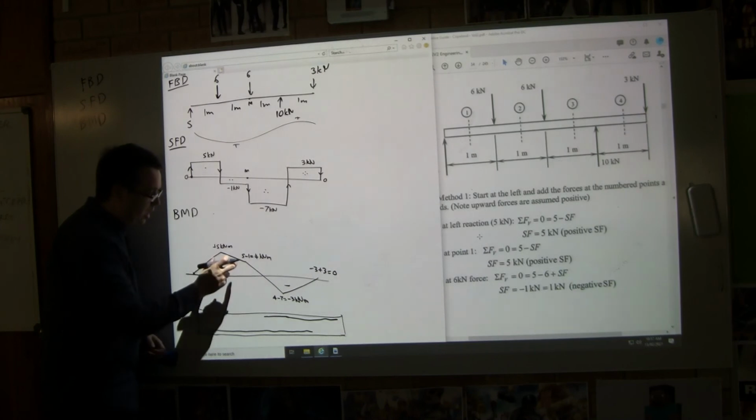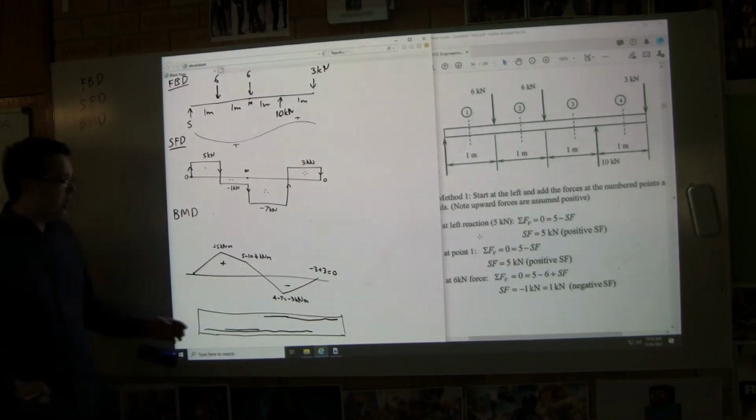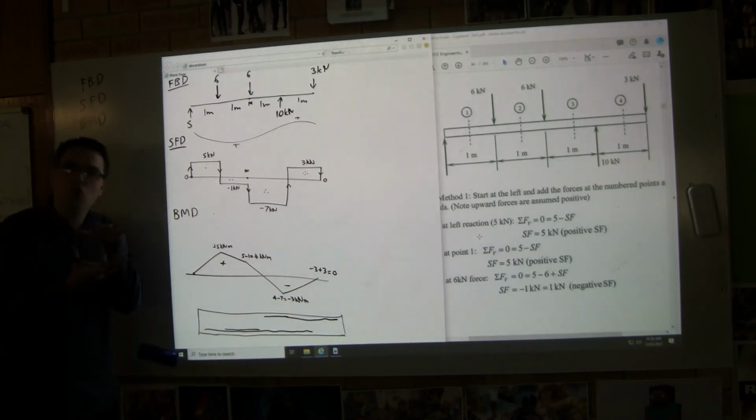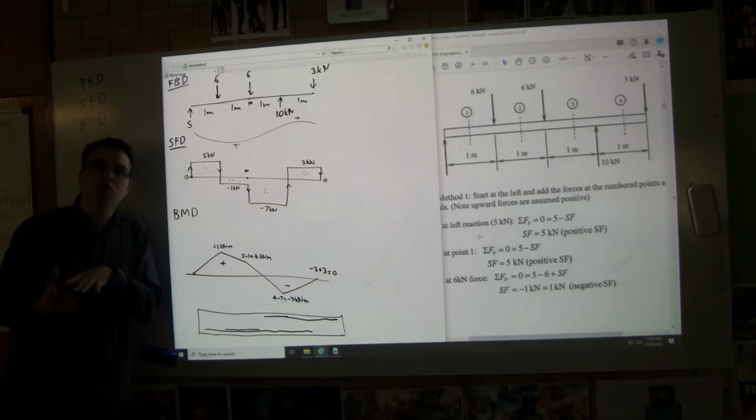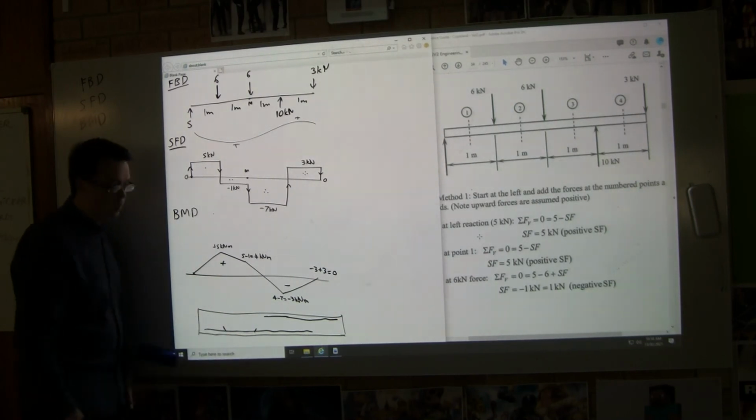Now, because our maximum is here, we might add some extra steel in that location. Now, that kind of looks like it's adding an extra row of steel, and we can do that. But sometimes we can squash extra bars of steel in between, in which case, in a diagram, we'd just show some extra bars in between there.